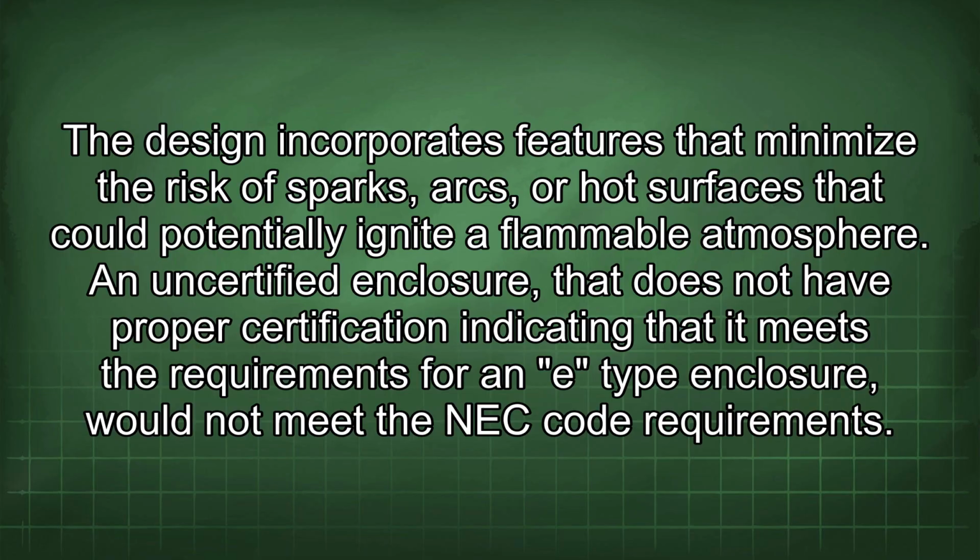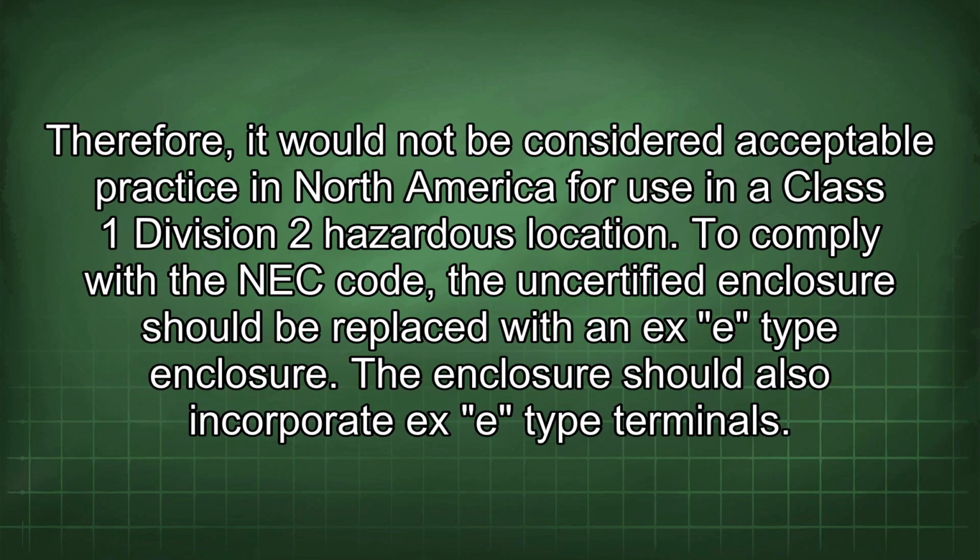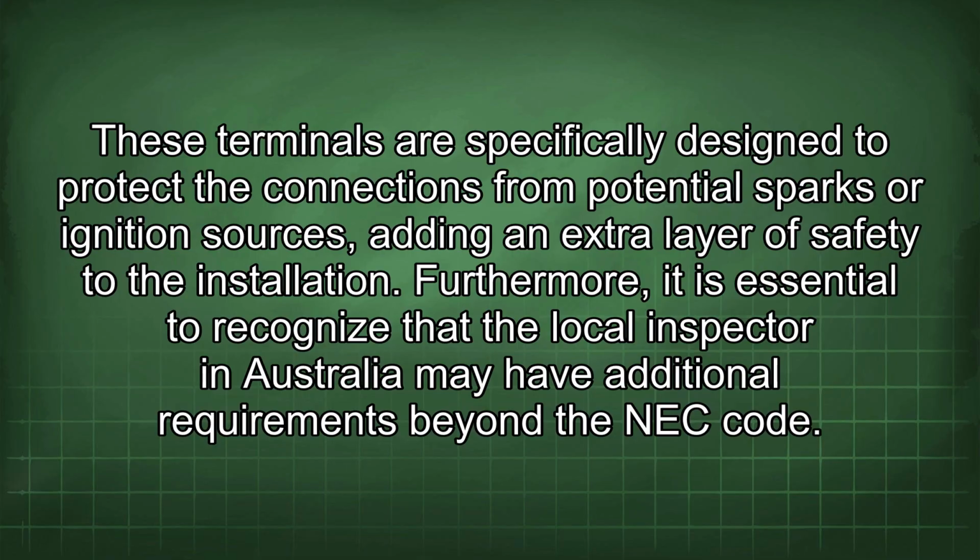atmosphere. An uncertified enclosure that does not have proper certification indicating that it meets the requirements for an E-type enclosure would not meet the NEC code requirement. Therefore, it would not be considered acceptable practice in North America for use in a Class 1 Division 2 hazardous location. To comply with the NEC code, the uncertified enclosure should be replaced with an XE-type enclosure. The enclosure should also incorporate XE-type terminals. These terminals are specifically designed to protect the connections from potential sparks or ignition sources, adding an extra layer of